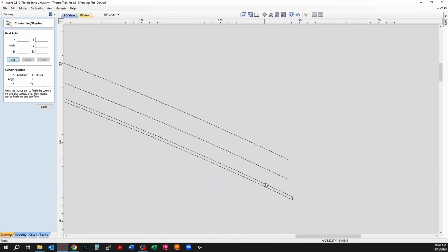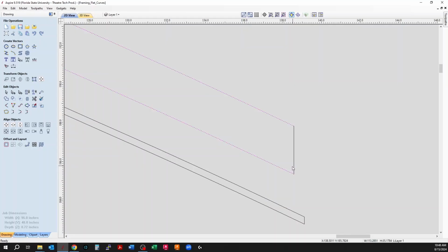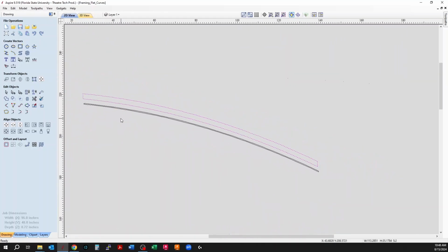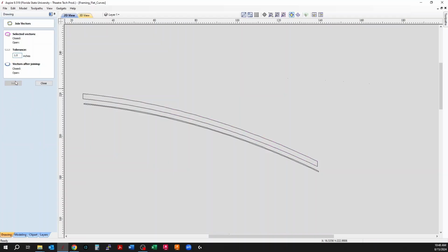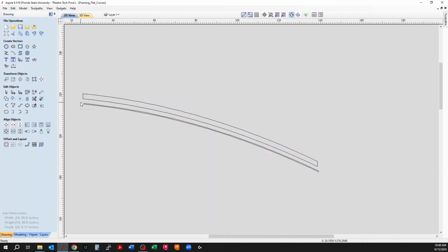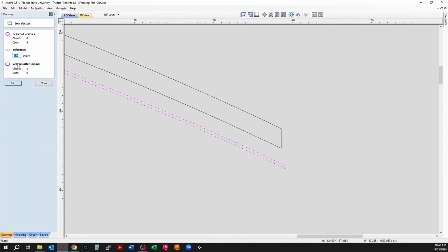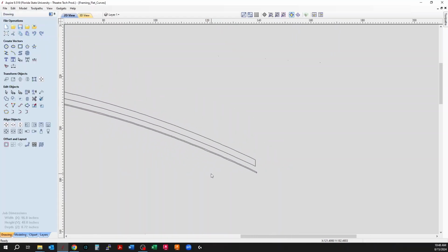and then there's that. Now you want to make sure that these shapes are closed, because right now they're all individual lines, right? So I've got that. It's got the end that's already closed. I'm going to close that open to a closed one, and I'm going to close up this shape as well. So just make sure all that stuff's selected. 4 open to 1 closed. There it is. So that's all joined together.